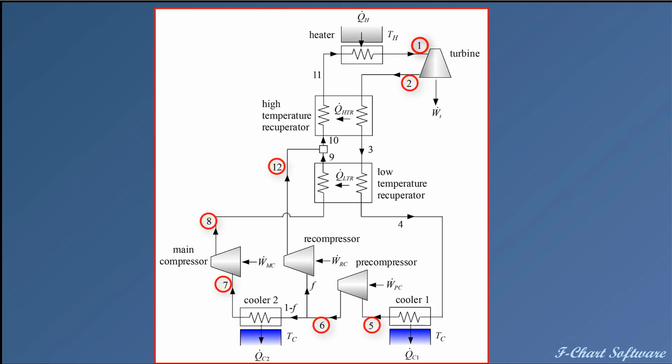But this approach does two things for me. First of all, I can enter the equations one at a time, so again that makes debugging easy, and second, I can start the iteration process from a very good set of guess values, which makes converging easy.